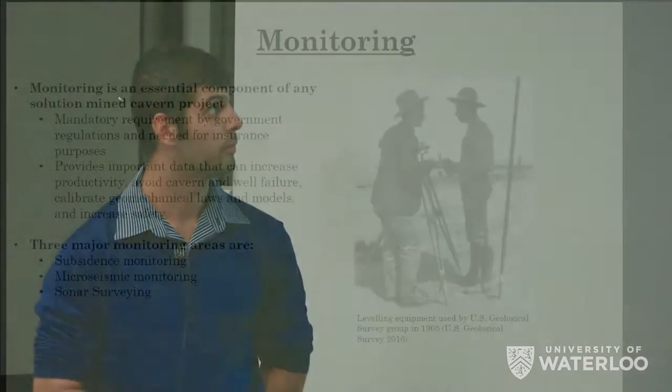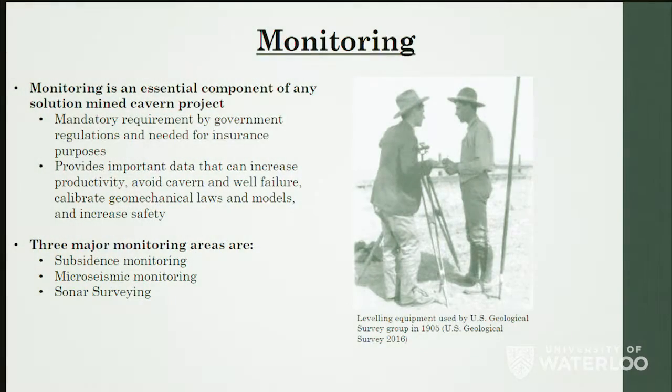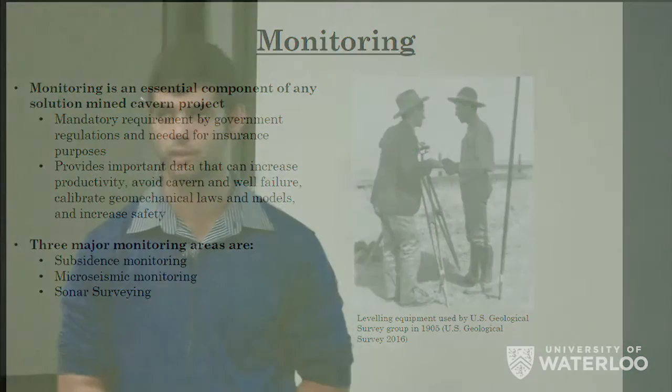But the last phase is monitoring. Monitoring is a mandatory requirement by government regulations, and it's needed for insurance purposes. Monitoring provides important technical benefits, such as it can calibrate geomechanical laws and models, it can avoid cavern and well failure, and it can increase safety. The three major monitoring areas are subsidence monitoring, microseismic monitoring, and sonar surveying.